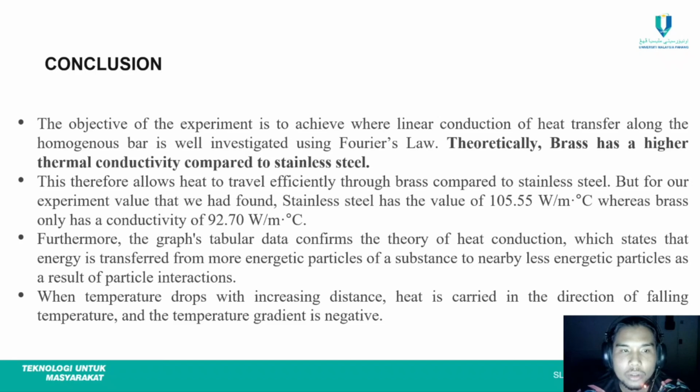For the conclusion, the objective of the experiment is achieved, where linear conduction of heat transfer along the homogeneous bar is well investigated using Fourier's law. Theoretically, brass has a higher thermal conductivity compared to stainless steel. This therefore allows heat to travel efficiently through brass compared to stainless steel. But for the experimental values that we found, stainless steel has a value of 105.55, whereas brass has only a conductivity of 92.70 watt per meter Celsius.